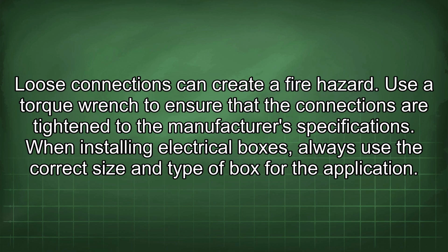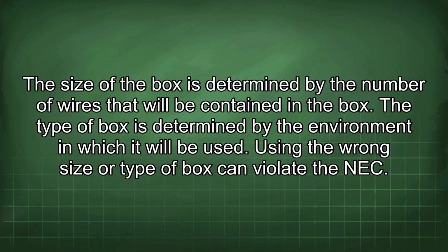When installing electrical boxes, always use the correct size and type of box for the application. The size of the box is determined by the number of wires that will be contained in the box. The type of box is determined by the environment in which it will be used. Using the wrong size or type of box can violate the NEC.